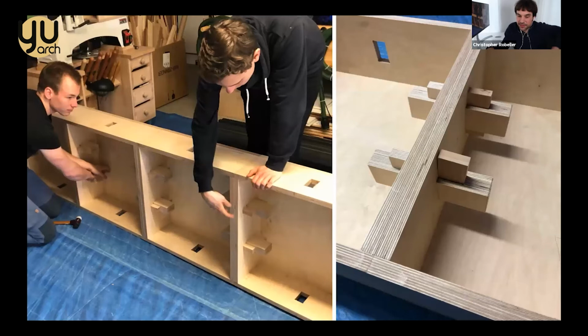And yeah, here you can see how the students were in the very beginning thinking of joints, right? We make these lightweight boxes. How do we join the boxes? And the idea was really to, again, use the wedge joints, where you have the possibility to squeeze and pull things a little, which is extremely important. Things, when you put them together on site, they are not going to be exactly where you are, and it's really helping to think of that in advance, give it some possibility to squeeze something together, to push things a little. Wood is a sort of flexible material, but you need to be able to apply the right force.